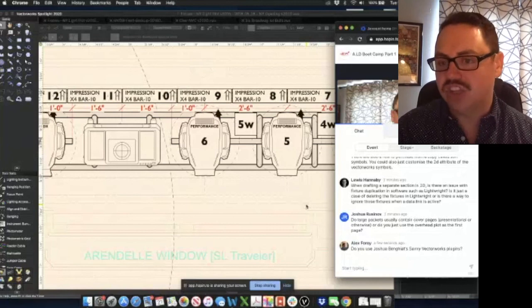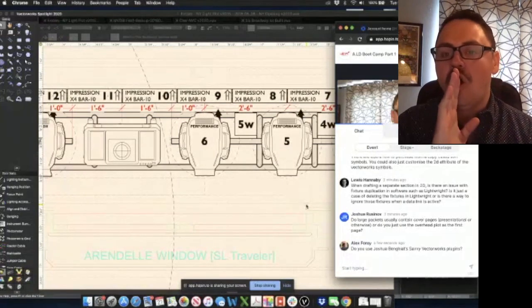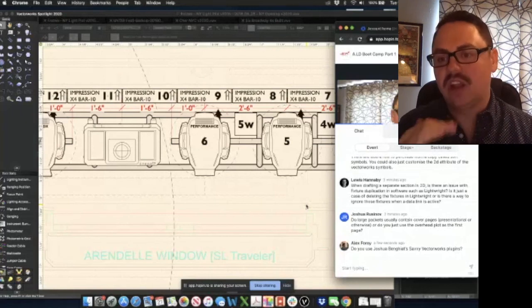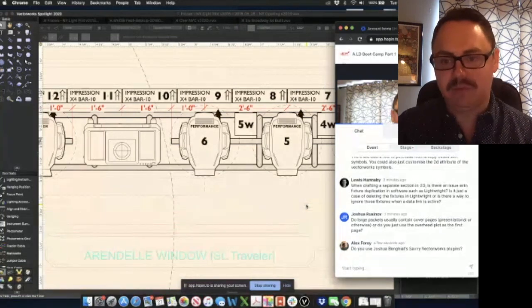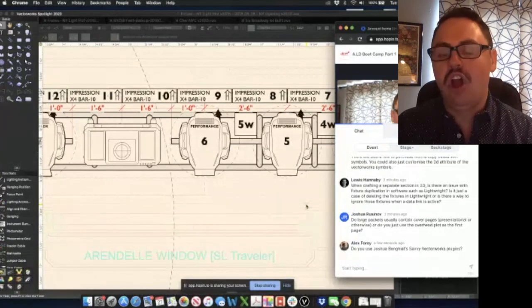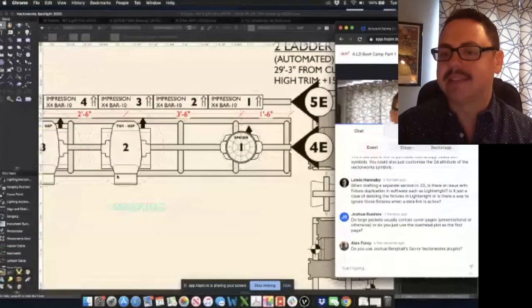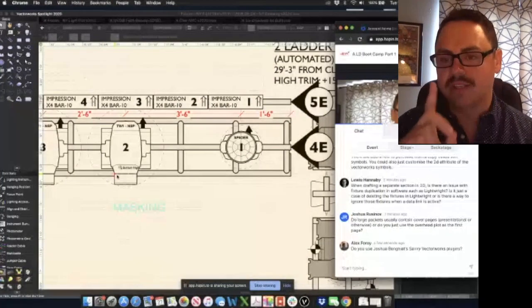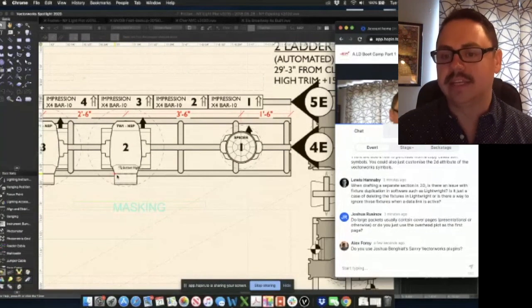All of my section lights, because I will sometimes do different sections or a front of house section, an elevation, everything else, those are actually separate symbols for me that do not have the lighting information. My only symbols that have lighting information that would be pulled into the Lightwrite are the actual ones that are shown in the drawing in the overhead or on their specific page and have that information. So anything in my drawing, the symbol is only there as a light one time. Every time else, it is just a symbol.